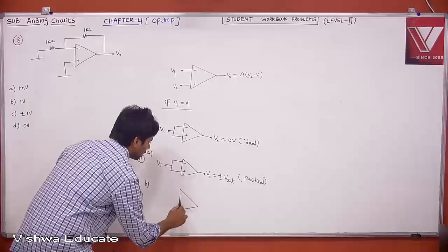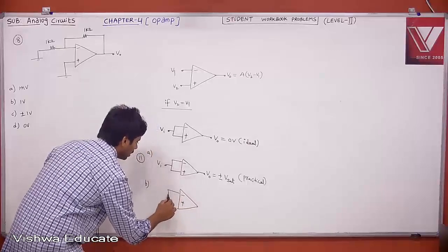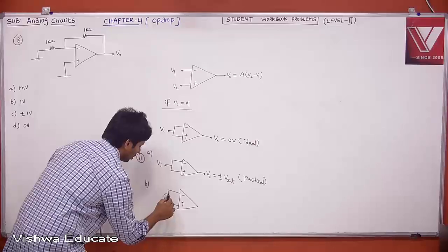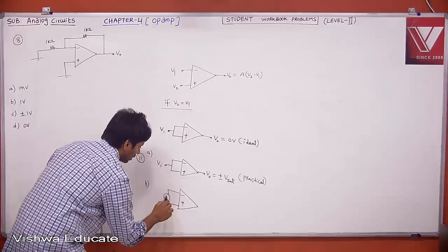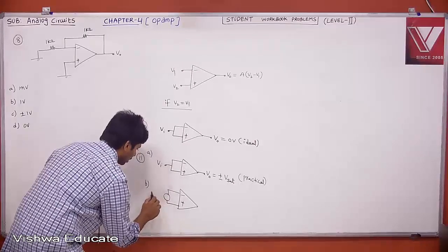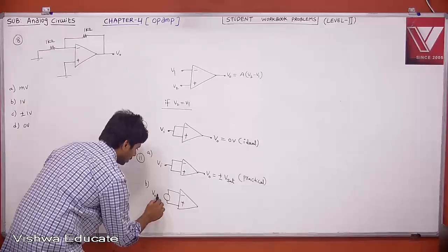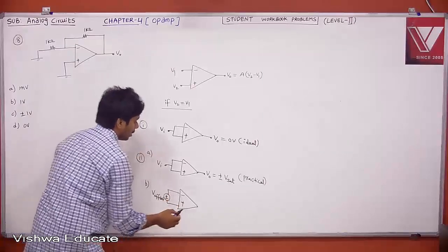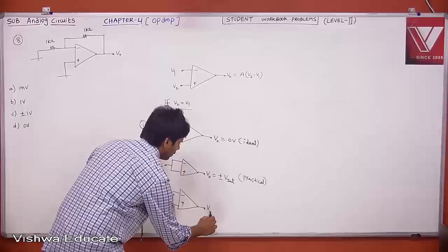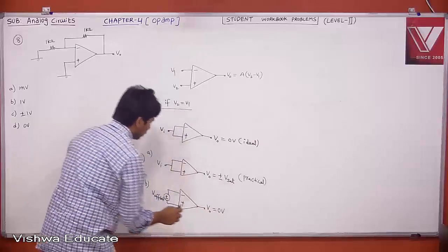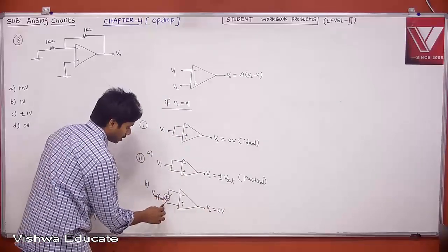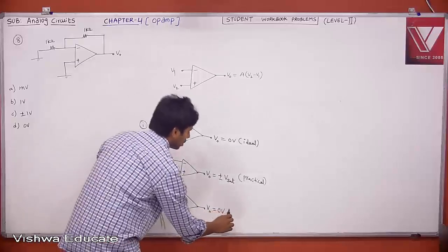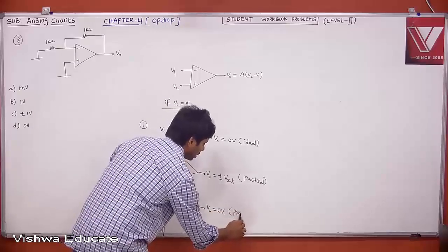You can connect a source between minus and plus and create some offset externally. It could be plus or minus, we don't know, but this is your offset. We need to create a voltage source, V offset, plus or minus, we don't know which. Then your output voltage will be 0. We need to adjust this such that your output voltage will be 0. This is your practical scenario.